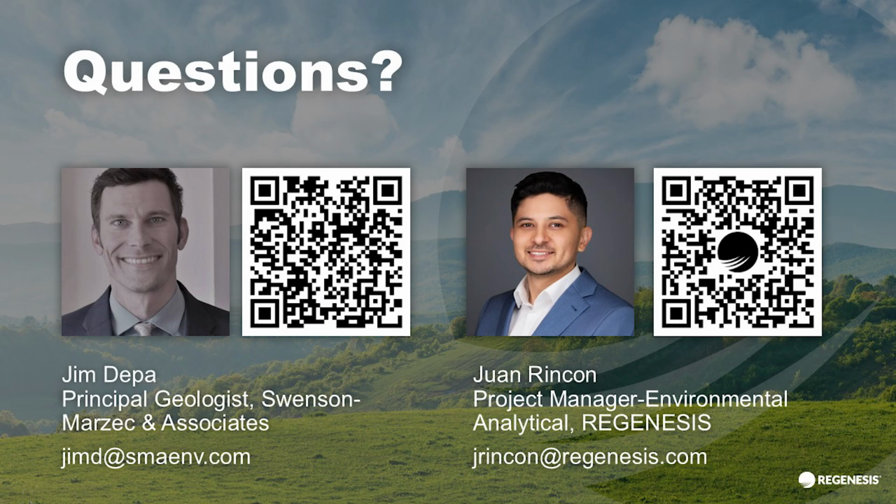Okay, thanks, Jim. So let's see, we have a question for Juan here. Juan, the question is, how do I determine the required flux tracer length for my site? Thank you, Dane. So we usually recommend to deploy it in the entire screen saturated section. Flux tracers come in 5, 10, 15, up to 30 feet lengths. And we recommend deploying it, and it allows, even if you are thinking your site has a homogeneous lithology, to delineate clearly the vertical location. Of course, flux tracers are meant to be deployed in 2-inch wells built with PVC Schedule 40.